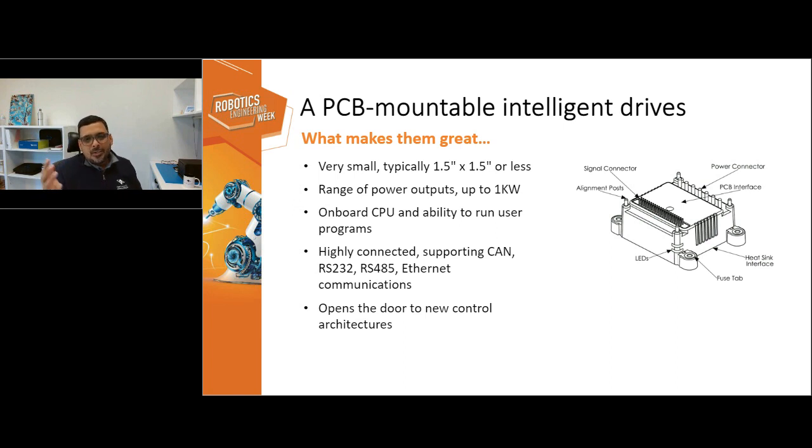On the motor side, you could talk to brushless, brushed, or stepper motors. When you're designing a healthcare robotics use case, most of them are brushless motors but there's a handful of stepper motors, so you can use the same drive and just set the motor type in NVRAM and intelligently configure each of these drives.